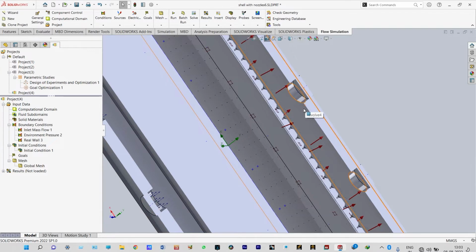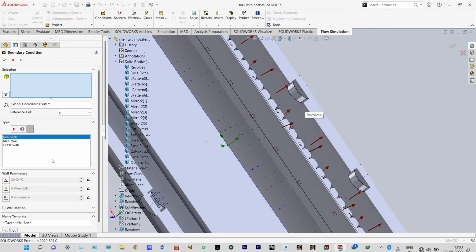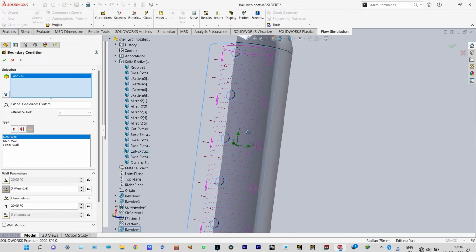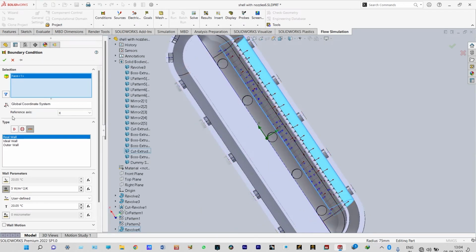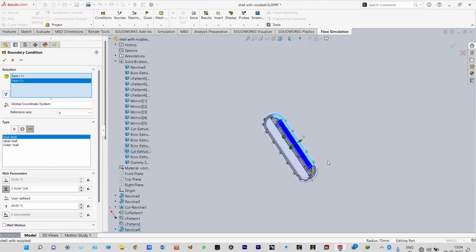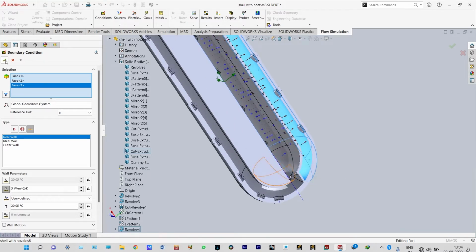And again from the other surface, that means from the top surface here itself, heat transfer will take place again with a different convective heat transfer coefficient. So boundary conditions, insert boundary conditions, walls, and from the top surface it will have a convective heat transfer coefficient of 5 watt per meter square degree Kelvin from this top surface, right? You can select this portion also. Done.